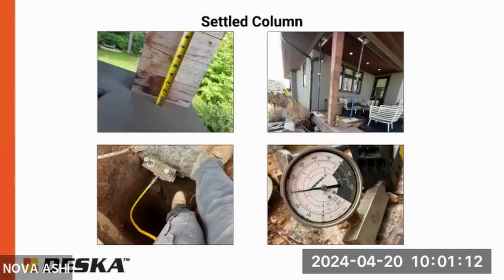So it varies. I mean, one example would be: is the porch supporting the roof or the house or something else, or is it just a slab that's not supporting an overhang or anything of itself? You'll notice that in new construction, a lot of the basement foundations bump out for the stoop so that the footing is the same depth as the rest of the foundation. But it varies. If the home is 50 years old and the stoop has settled an inch, and it doesn't seem like there's been movement for a long time, then structural polyurethane, maybe that's an adequate repair.